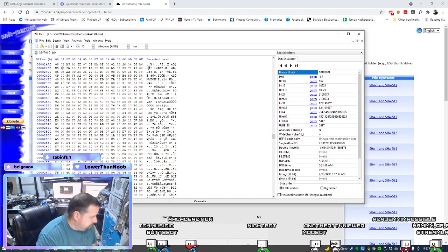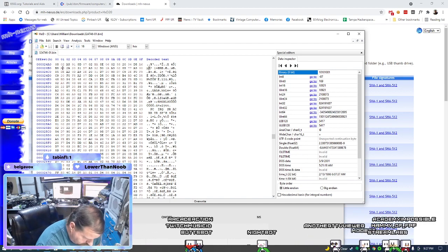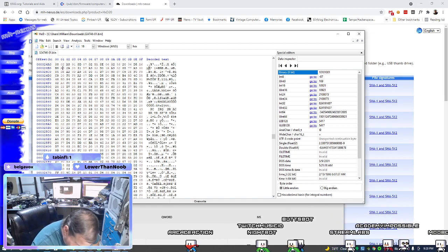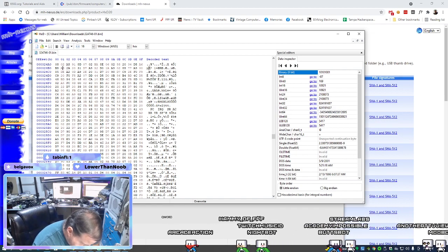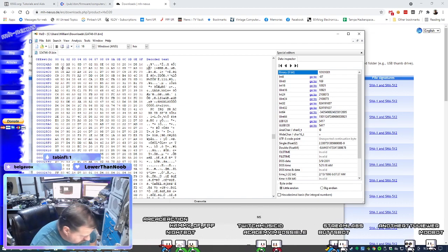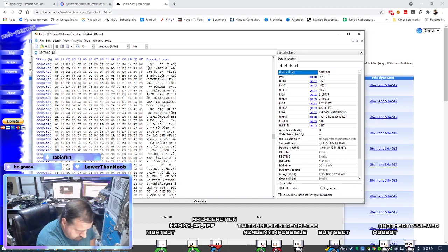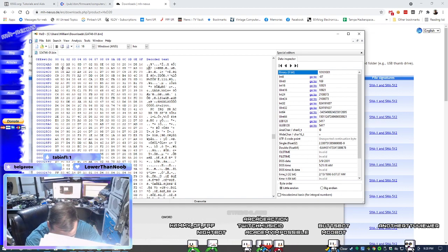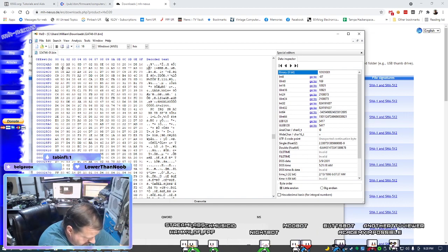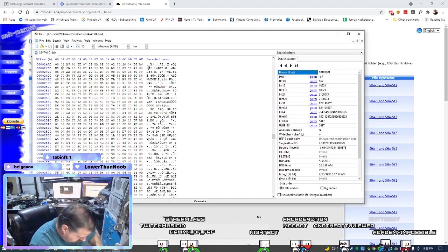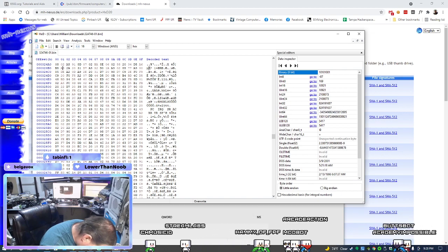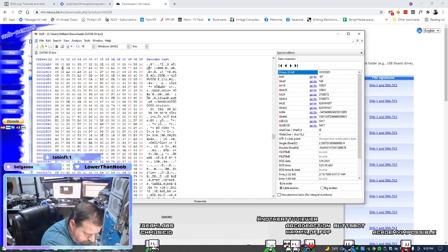Did a reset. I know this is a stock editor. I don't know if I need to put this with the same paperclip. That's the other editor. So what I'm gonna do is let's see if the logic probe is showing any activity on the output pins. Still no output on the video chip.